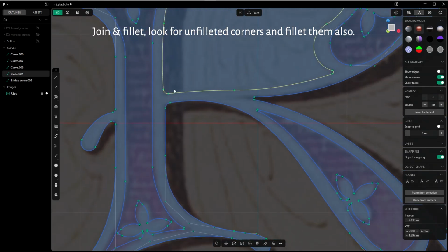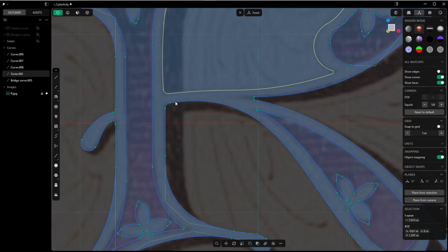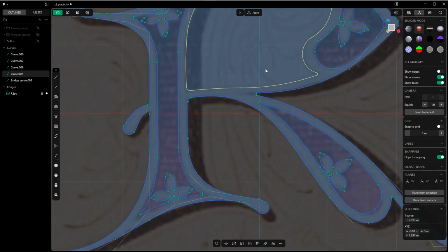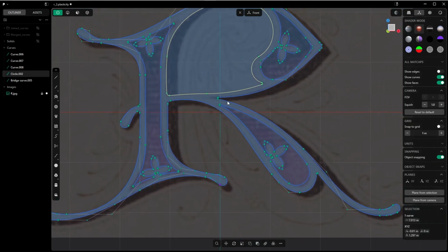That's another way of rounding up the corners. You know, the first one was the one with the tangent circle, creating a tangent circle and on both edges, trimming the sharp corner. That's the first method of rounding edges. The second method is filleting right away. I wanted to show you both.